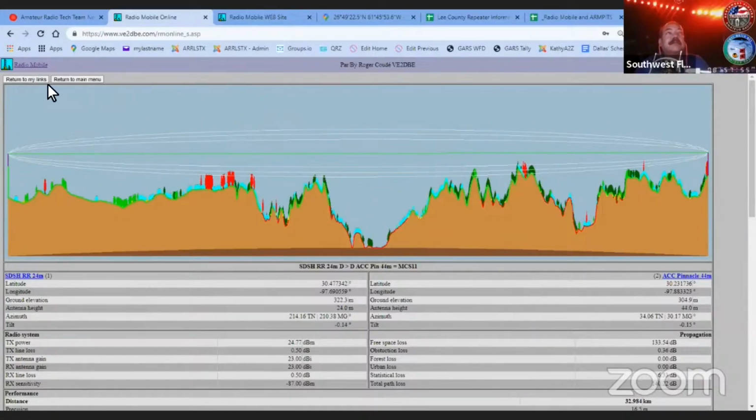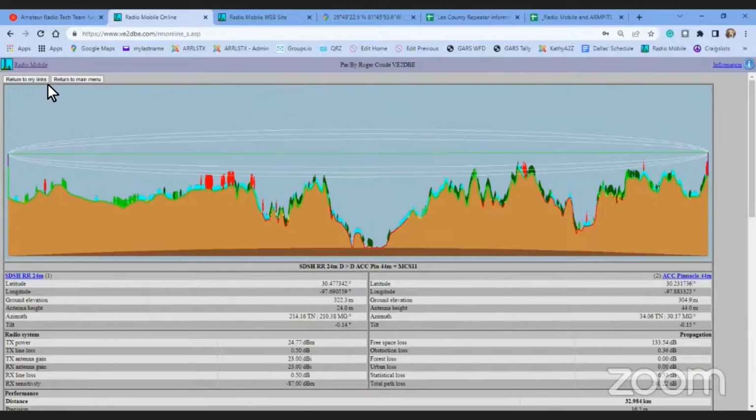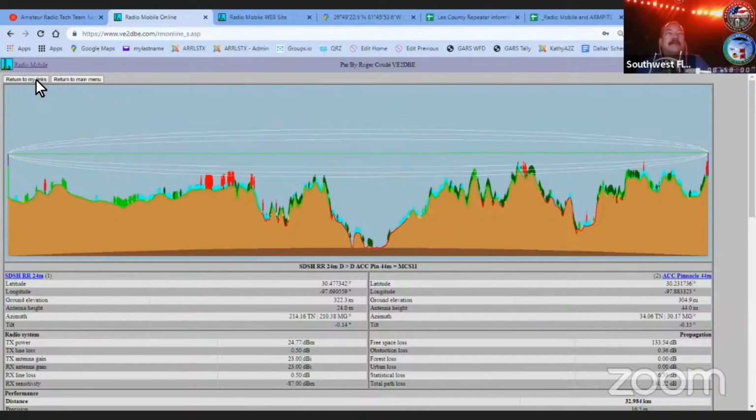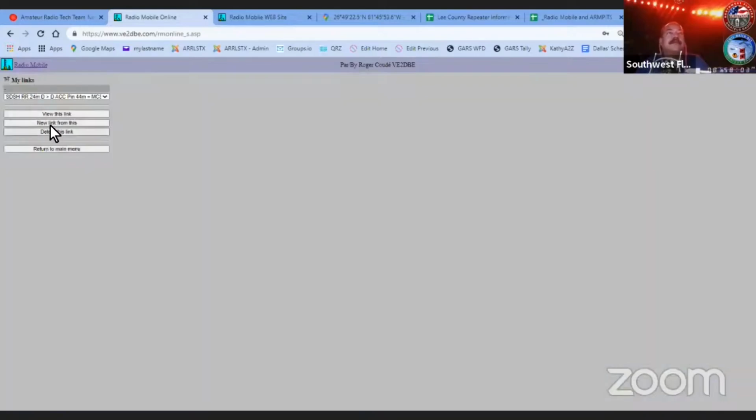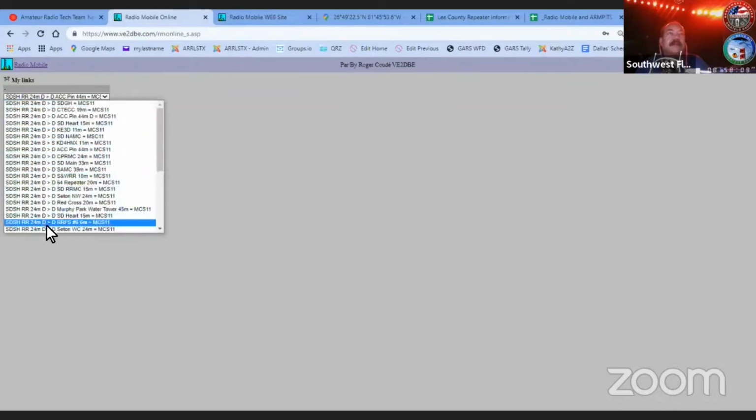My station uses a 400 megahertz STL, or studio transmitter link, from our downtown office at the Wink building. On our antenna, there's a dish that faces down to Estero, and on the tower in Estero, there's another dish, and we send our radio signal down to our tower on the STL with the internet as a backup. And believe it or not, when I was program director about 7 years ago, it started blinking out. We started losing it certain times of the day, and we'd be on backup 2 or 3 hours a day. And then finally it started getting to where it was out all the time.